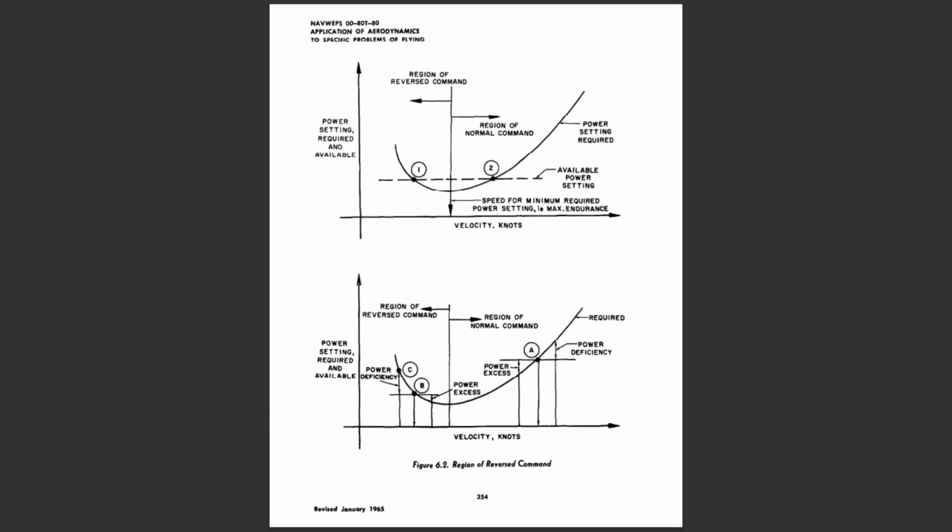If the airplane characteristics are high wing loading, low L/D, and low lift curve slope, the increase in angle of attack at point B may produce a transient motion in which the airplane does not flare. That is, the increase in angle of attack may produce such rapid reduction of airspeed and increase in rate of descent that the airplane may be incapable of a flaring flight path without an increase in power setting. Such characteristics may necessitate special landing techniques, particularly in the case of a flameout landing.